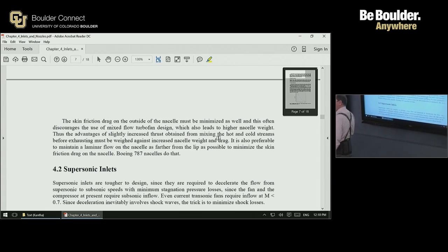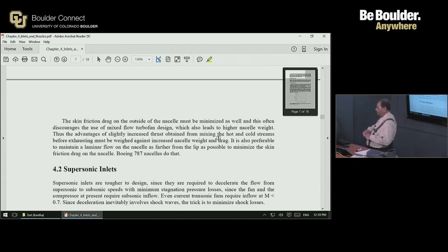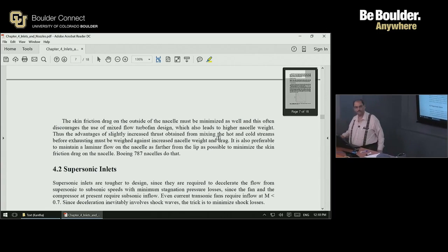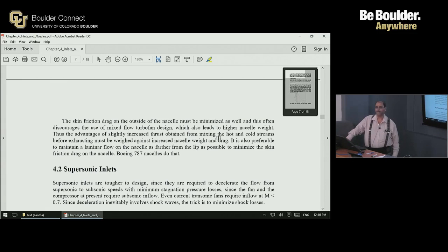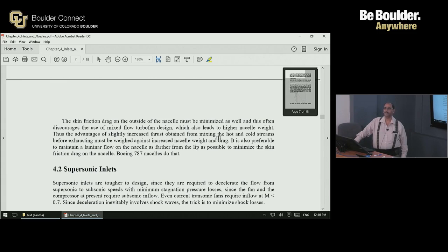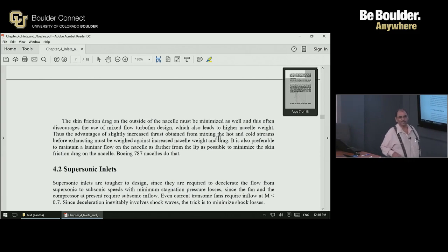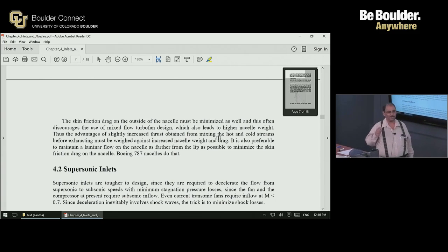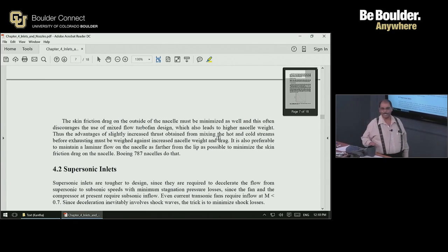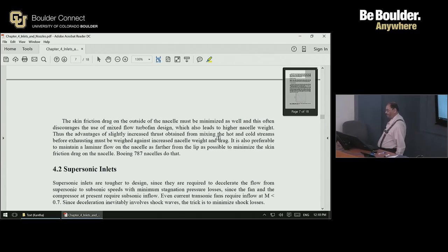The Boeing 787 is designed with a laminar flow nacelle. I think I did some calculations and showed that the drag was reduced by a few hundred newtons. Okay, this is what the airframers are doing, trying to squeeze out the drag as much as possible by doing things like that, because drag reduction shows up in terms of reduced fuel consumption.